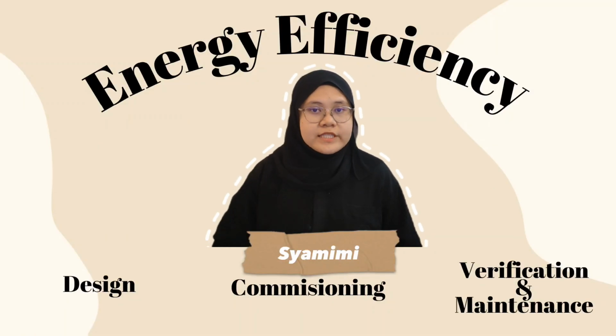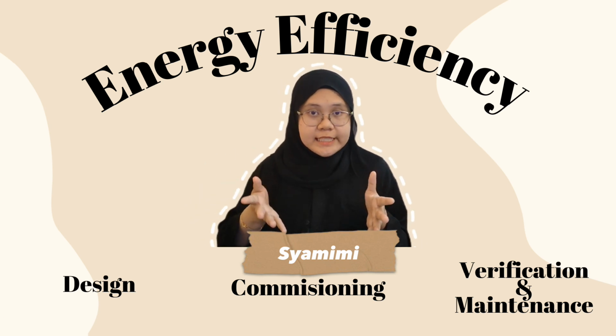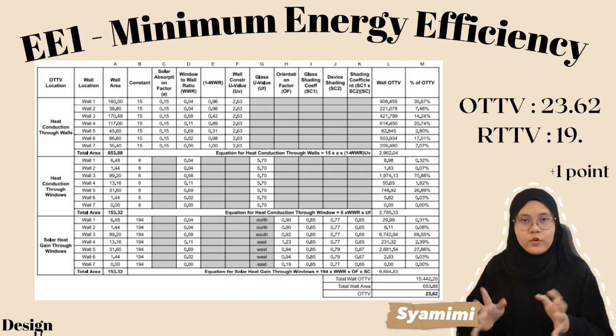The energy efficiency for this building is excellent, as it scores 31 points out of 35 based on the Green Building Index 2. There are three main parts of this criteria, which are design, commissioning, and lastly, verification and maintenance. Firstly, OTTV is a measure of heat gain into the building through the building envelope.